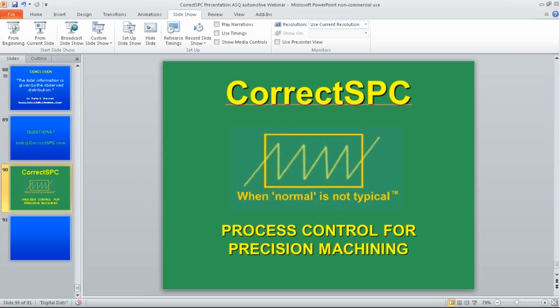And then another comment: I see danger in allowing a goalpost approach to specifications rather than minimizing variation about the mean. Well, again, if you compress the control limits, you increase the operator intervention. So that's the danger I'm talking about, and you need to balance that variation. If they want to call it goalpost, it's identified statistically why we use that.